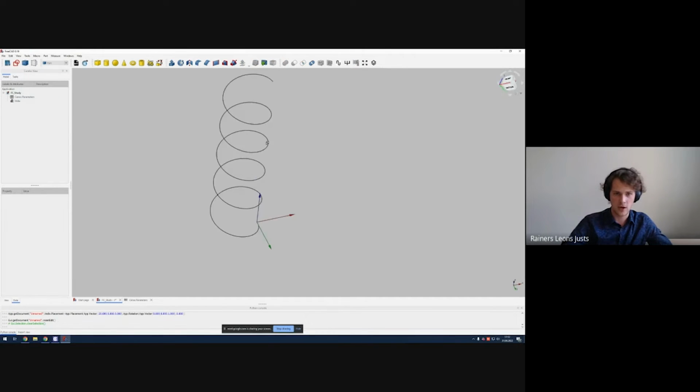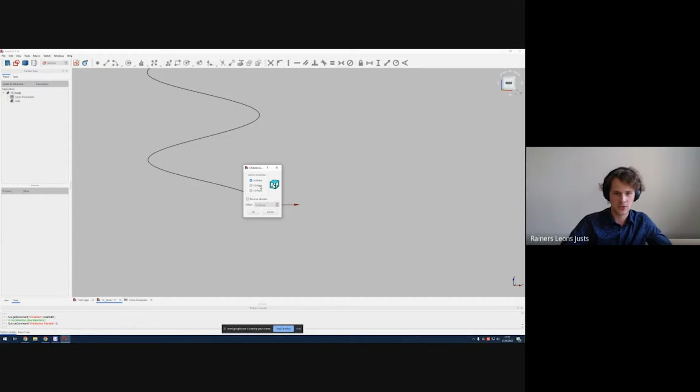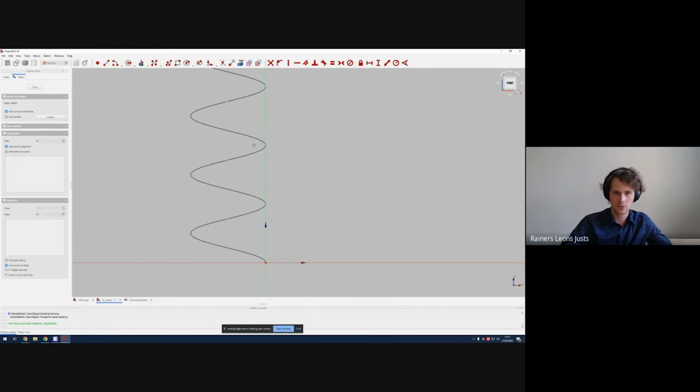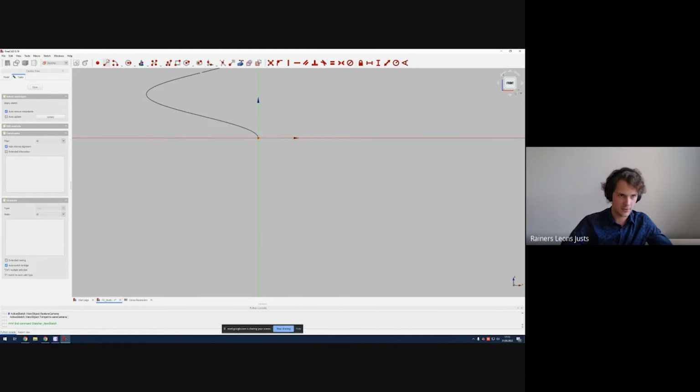And now that I mentioned that we are going to be adding a feed line, so let's do that using the Sketcher workbench. So I'll open up the Sketcher and create a new sketch on the Z and X plane. And as you can see, we have a sort of a sine wave going upwards. And we'll be defining the feed line as a singular line in the model. So let's just place down the line. And now let's apply some fixed lengths to it.